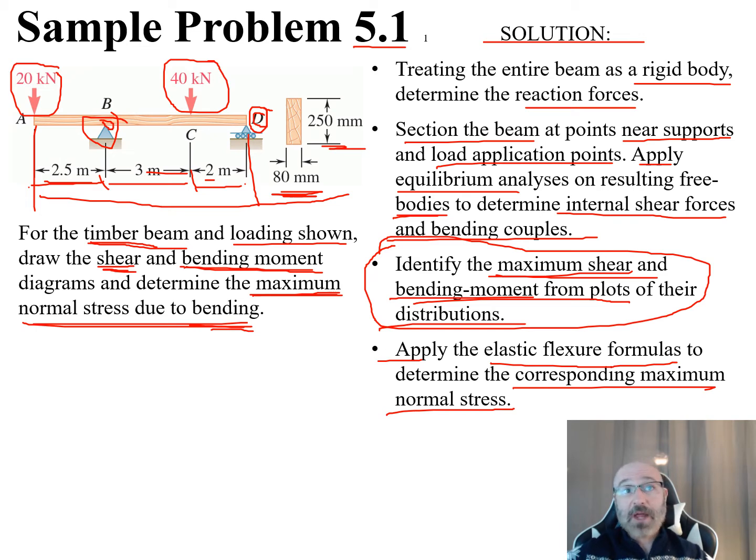B, I'm solving for my bending moment diagram. And C, I need to find that maximum normal stress due to bending right there. So I have those all clearly laid out on my setup page.